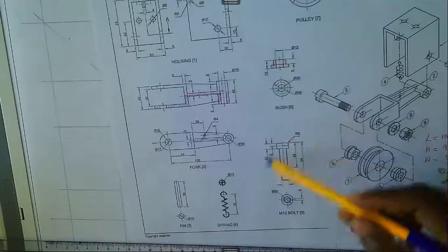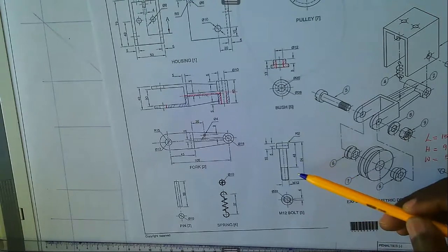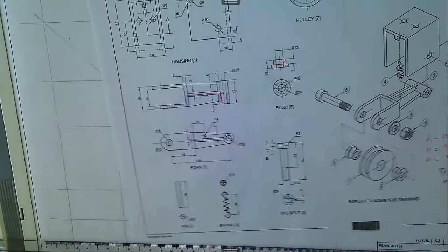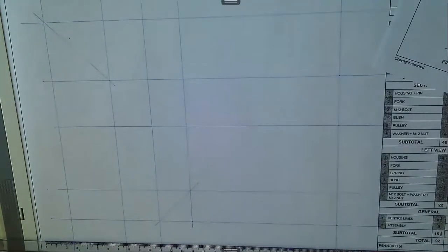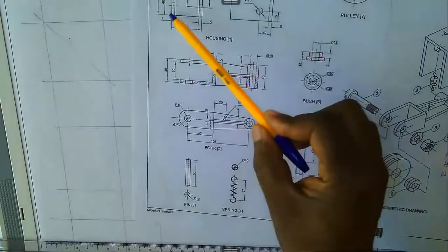Now, if you are looking at this, in terms of our size, we mixed the size of the M12 bolt, which is actually 64. Because we do have space available, we can say 64 minus 50, we have got 14 millimeters. 14 millimeters divided by 2. So either side we can add 7 millimeters in order to accommodate the M12 bolt, because that is the longest size. Because we had considered this one from here to there.